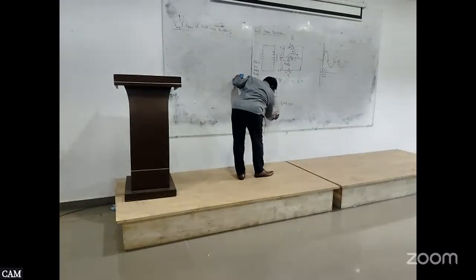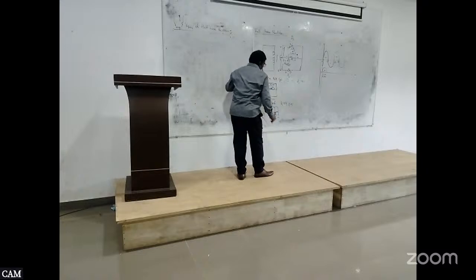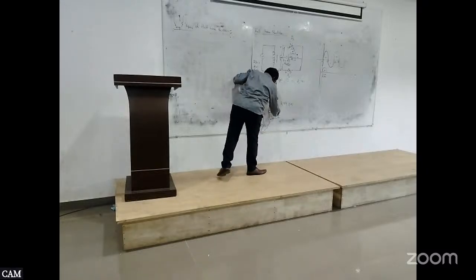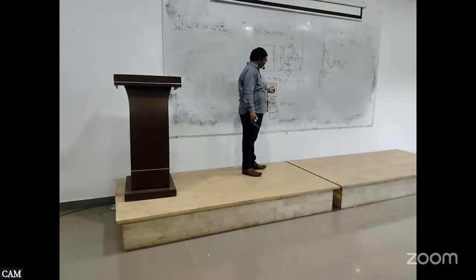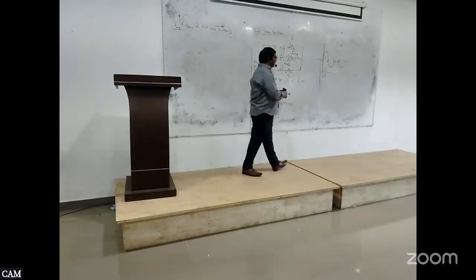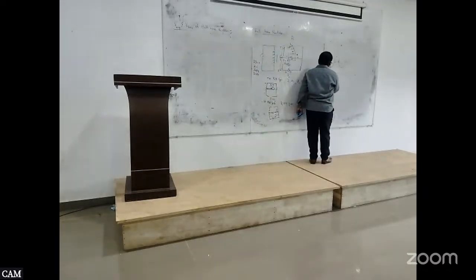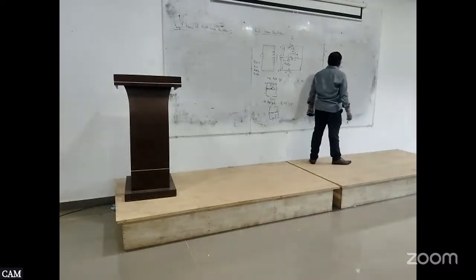So the current will flow like this. Okay, see how the current direction in both cases, with respect to the resistor, is positive to negative, positive to negative, positive to negative. So here during the negative half cycle also we will get a positive curve only.